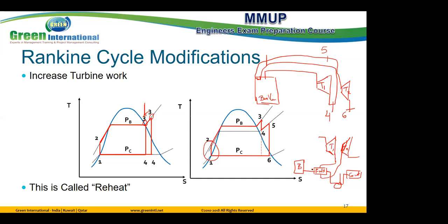And we have different types of this one. Sometimes it is closed like this, sometimes it's open. Closed goes like this, like a default heat exchanger. Sometimes it's open and mixes with this one to make intermediate pressure and goes with another pump to the boiler and so on. But overall, for the Rankine cycle, how many stages can we use as reheat and how many stages can we use as regeneration and so on, nowadays this is worked out by software to reach the optimum output according to the input we use.